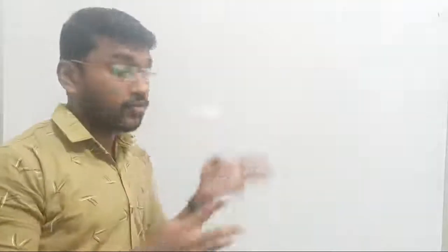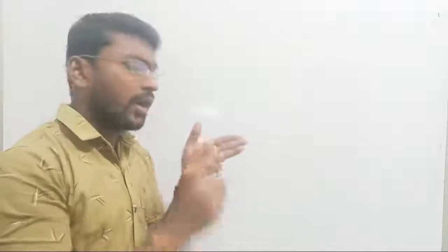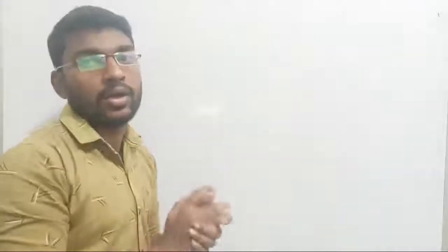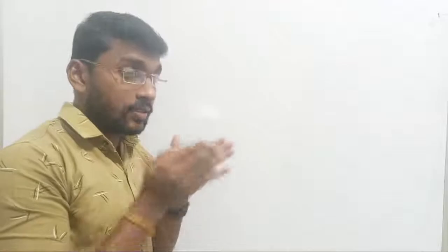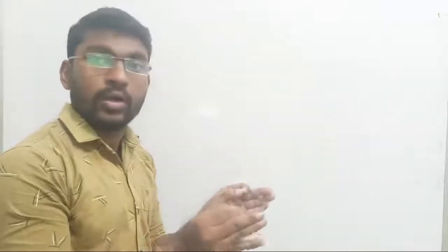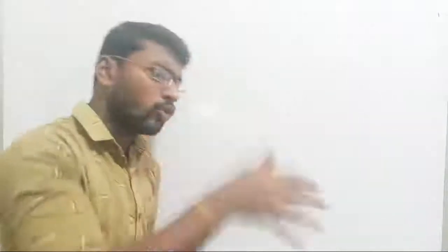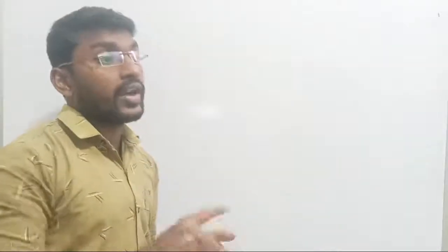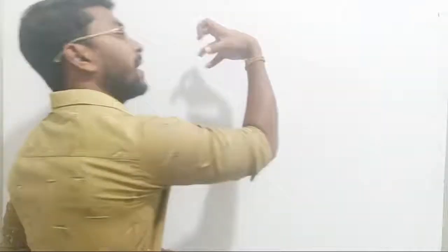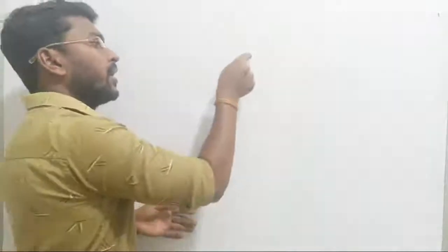Three phase. That is, if three phases are short circuited together, or three phases are short circuited together with the ground, that is called a symmetrical fault. The symmetrical fault is the only one that will consume or deliver the highest fault current from the alternator to the transmission line or to the ground. So in the transmission line point of view, three currents together carry the maximum current through the line. When I add those three currents, the magnitude becomes greater than the rest, like LG, LL fault, LLG fault. That is what I told you.